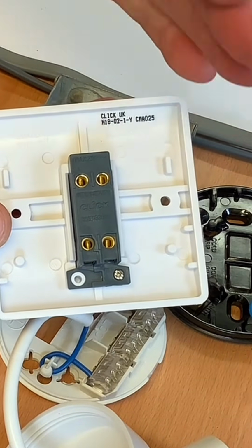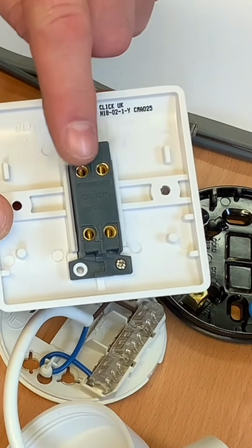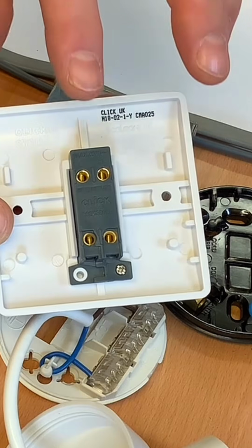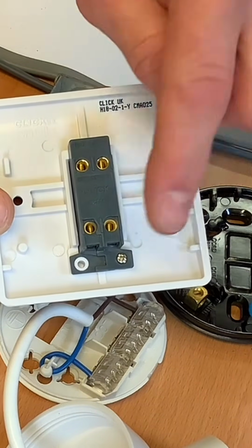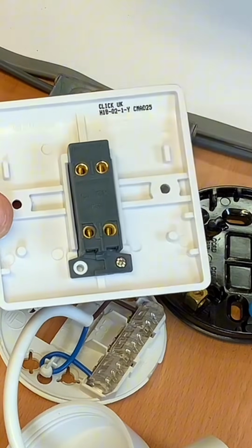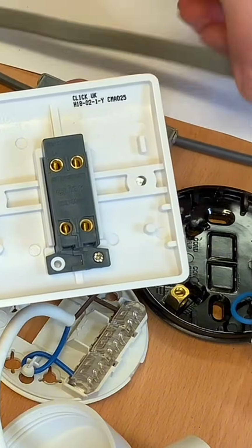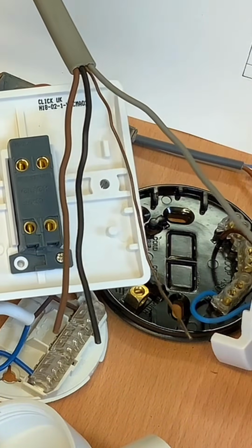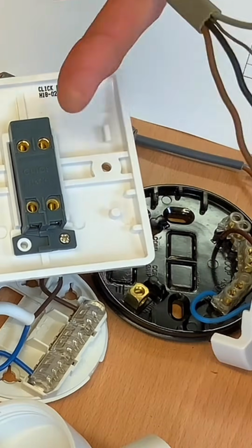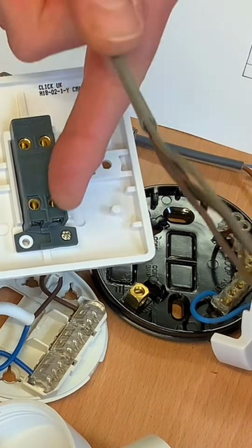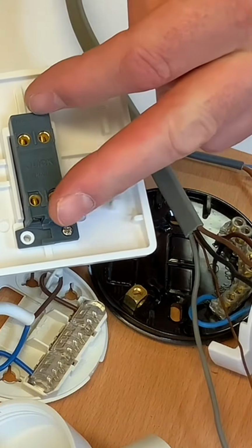It's important only that a cable coming in the top goes in here and here. So the brown and grey of a cable coming in goes in the top, and a cable, brown and grey, goes out the bottom and not across the side. So this cable, when it comes in, we use the brown and grey either in the top 2 or the bottom 2, and the one going out goes in either the top 2 or the bottom 2, and we'll see that in the drawing, and definitely not across the side. So the brown and grey of these wouldn't be connected across here.